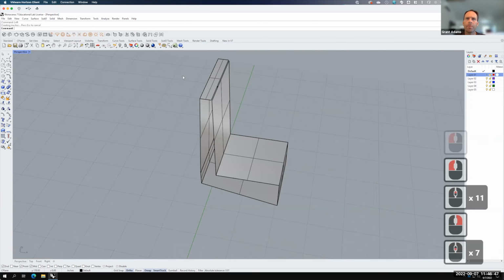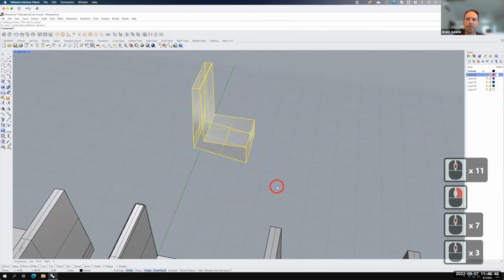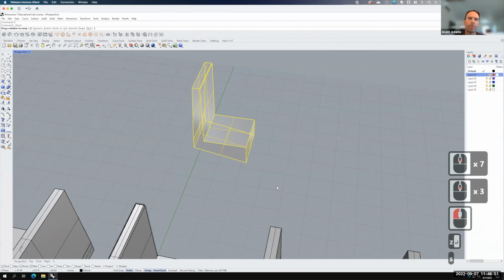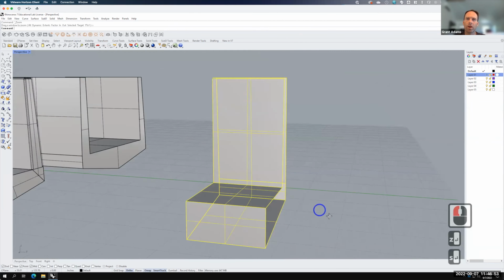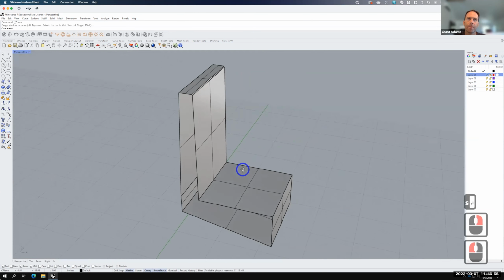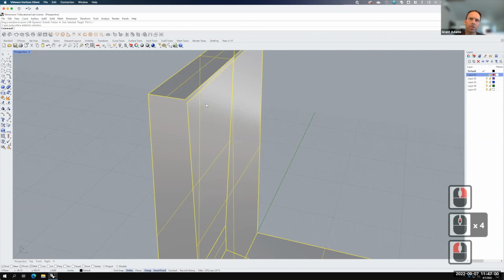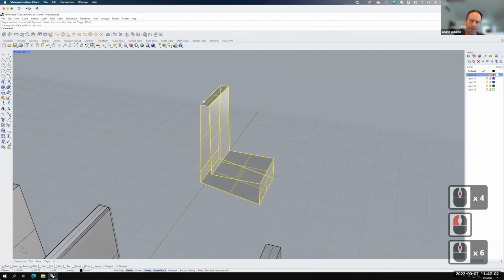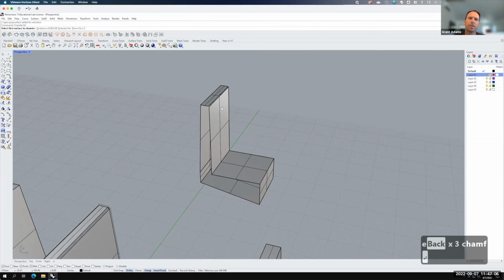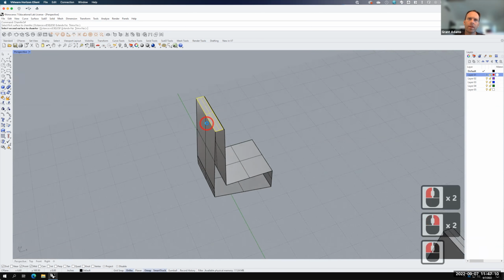Perfect. Let me recenter my zoom. So I'll select this object, zoom, followed by S for selected. Now I'm working on that object there. Let me go ahead, and it looks like those two didn't quite connect. Let's do a chamfer surface between this and this, between this and this.